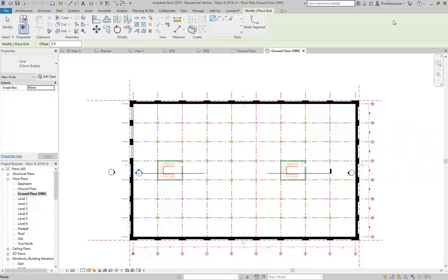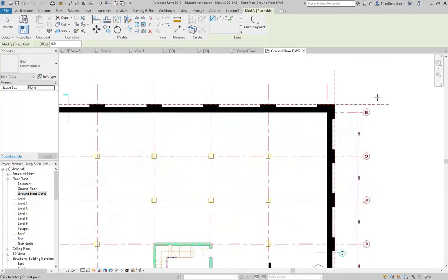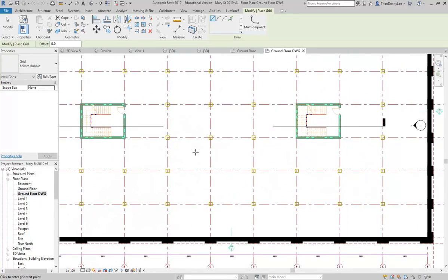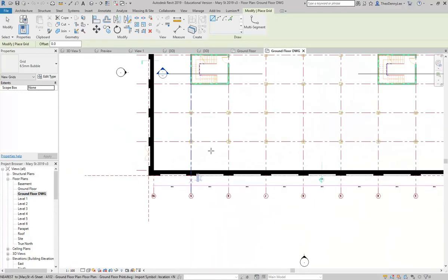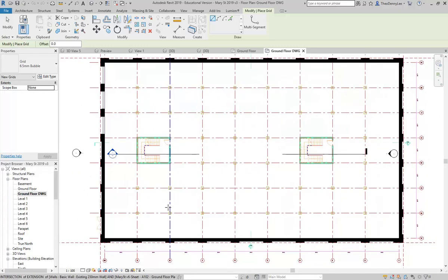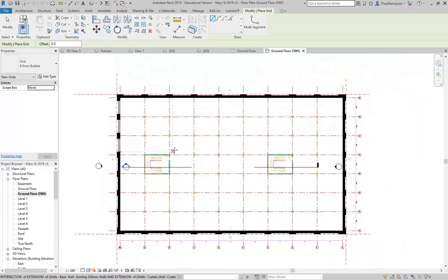So with the grid tool, I'm going to firstly just see what my numbers are. We're going to do it upside down this time, so I'll just go with that. Okay, so I've got the option there to use pick lines. So instead of drawing lines, I'm going to use pick lines, and then just pick my AutoCAD line work. And I'm just going to go with where the bubbles turn up. So the bubbles here are at the bottom.